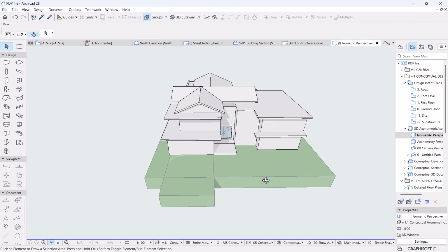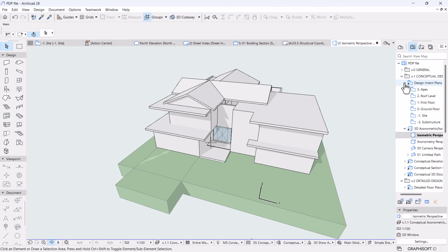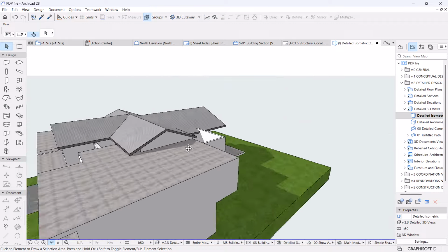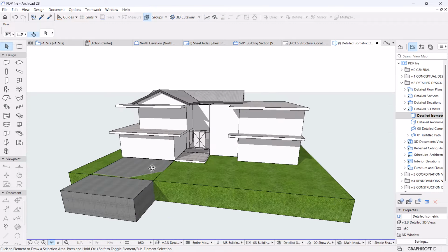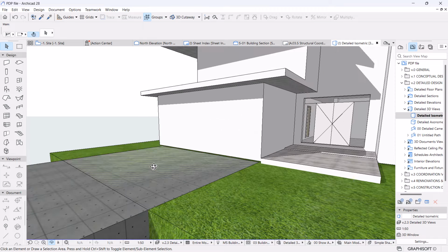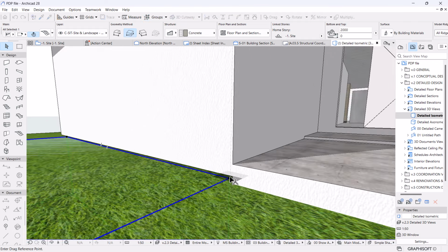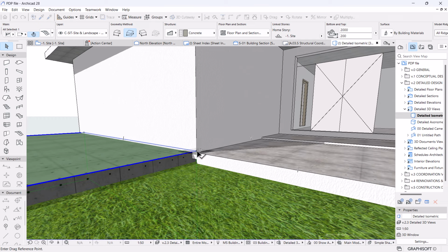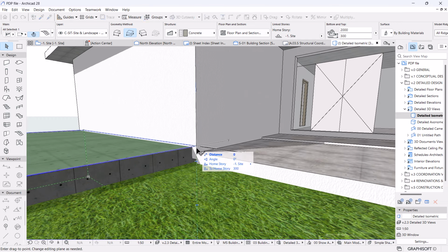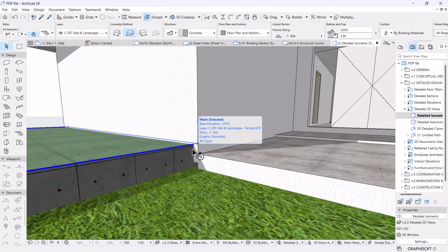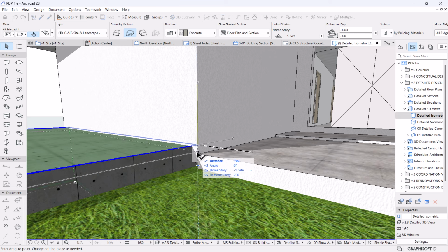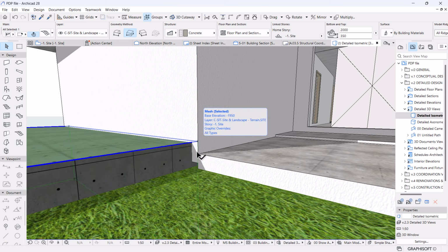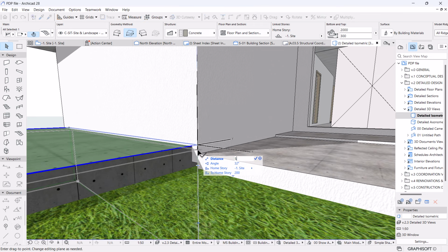So from 3D you will have something like this. We're no longer working on the conceptual, we are on isometric detailed design, so that we can project everything as it is. Okay, so here it is, and this should start on, this is 200, right? It has to start right on the ground floor finish. Normally we drop our garage slab by 50. So let's drop it by 50.